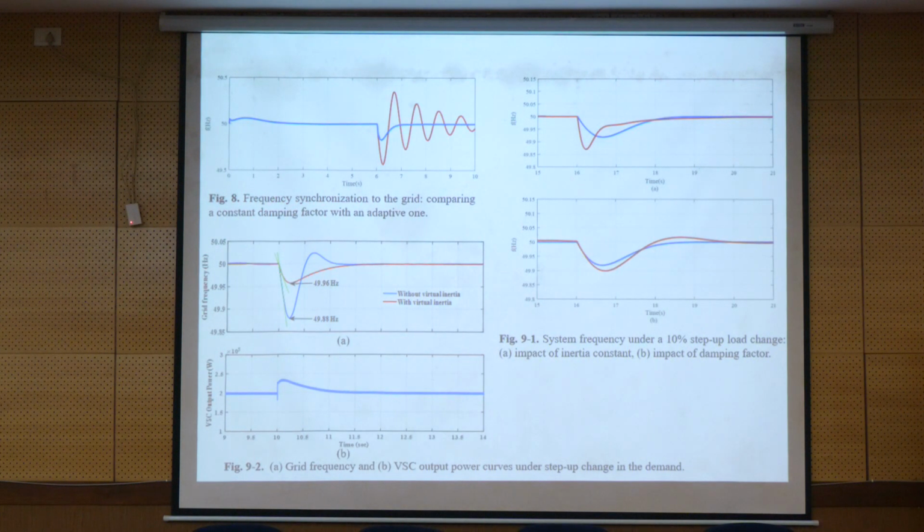But here we see that the systems are different, because sometimes you are in the grid connected mode, then you go to the islanding mode and again get back to grid connected mode. So this should be able to damp the difference, because you have a converter that connects to the load or to the grid. The dynamics of the load and grid are different, so the swing value will be different.